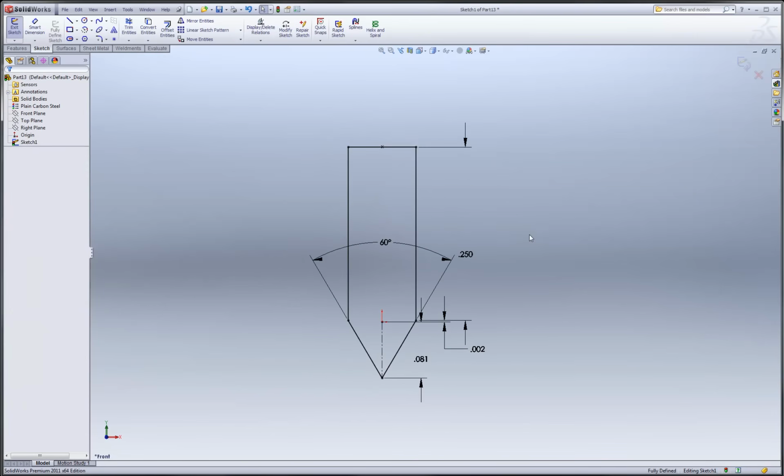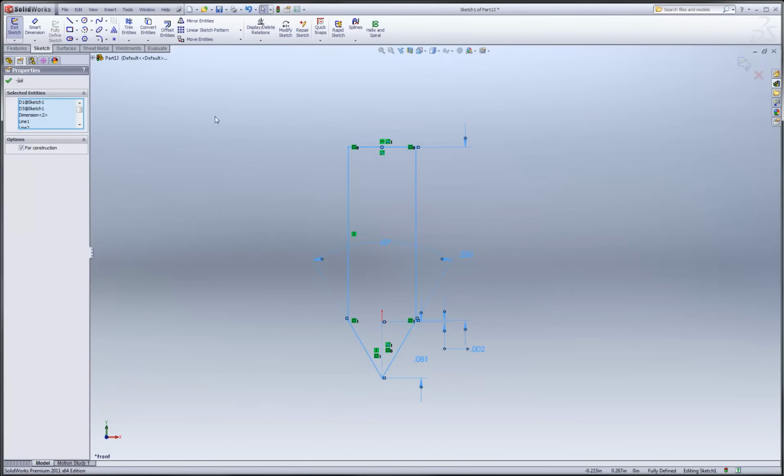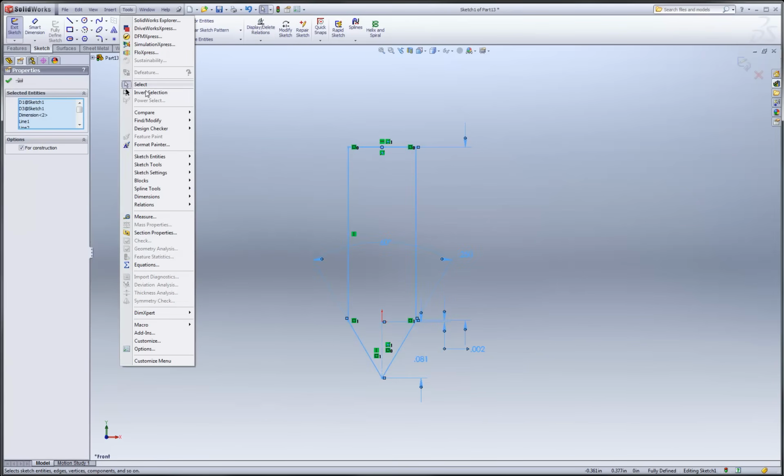We now want to convert this sketch into a block. By making it into a block, it can be saved as an external file, stored in a library, and reused for multiple applications. To create the block, we'll window select all the geometry, choose Tools, Blocks, Make.